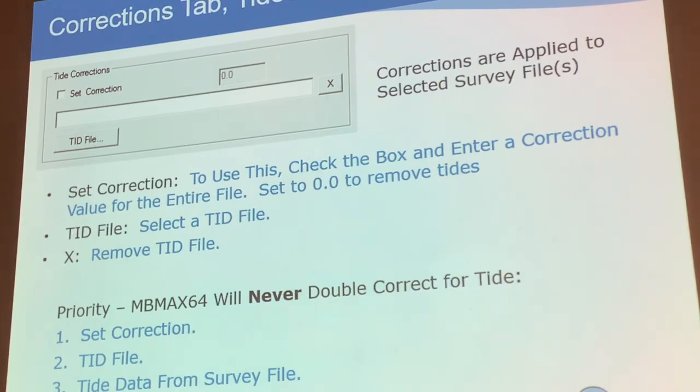But you can always check when you are doing the actual processing. You can use a sample and try to see what kind of correction it does. Because when you input the file, remember sometimes it's in elevation mode, sometimes it's in depth mode. So if you put depth mode, then the negative must be positive. So you must always check whether it's in depth mode or elevation mode, because it will change accordingly when you put in the tide. So it's quite important that you check the negative and positive with the sample data first. Then once you are sure, you can apply it to the full multi-beam data.